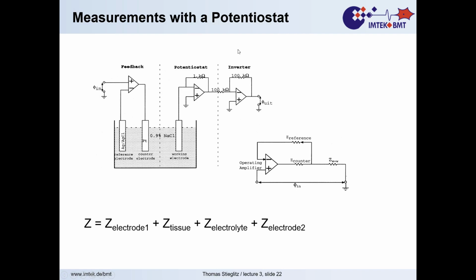You might know that if you have done an electrophysiology course or cell culture course with electrically active cells, or if you have done an engineering course in electrical engineering, measurement, instrumentation, if you measure something, you need the ground point. And you always assume if a current flows, that this does not influence your measurement. That's unfortunately wrong in electrochemistry. If a current flows, this current flow could influence your measurement somehow.